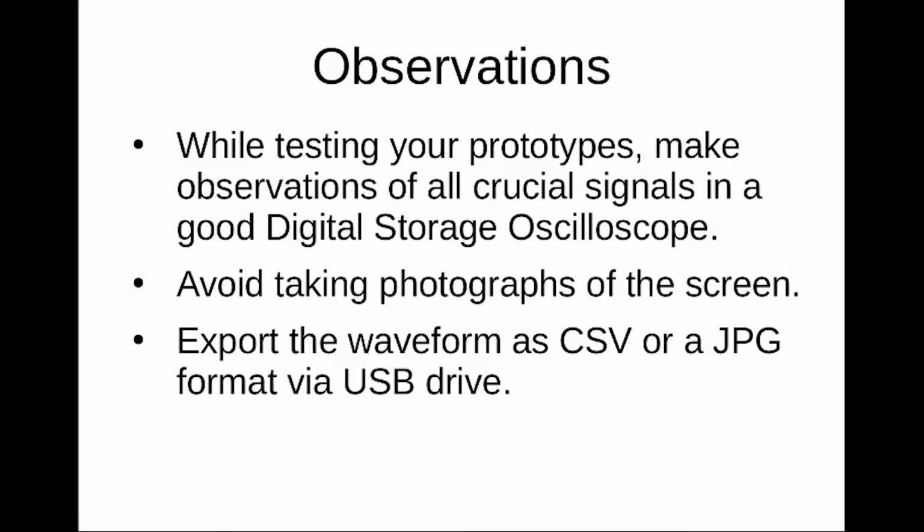Export the waveform as a comma-separated variable file, CSV file, which you can later import into MATLAB or a spreadsheet program like Excel and plot the waveform. Or you can export in a JPG format via the USB drive usually available in the oscilloscope. Learn how to do this from the oscilloscope manuals.